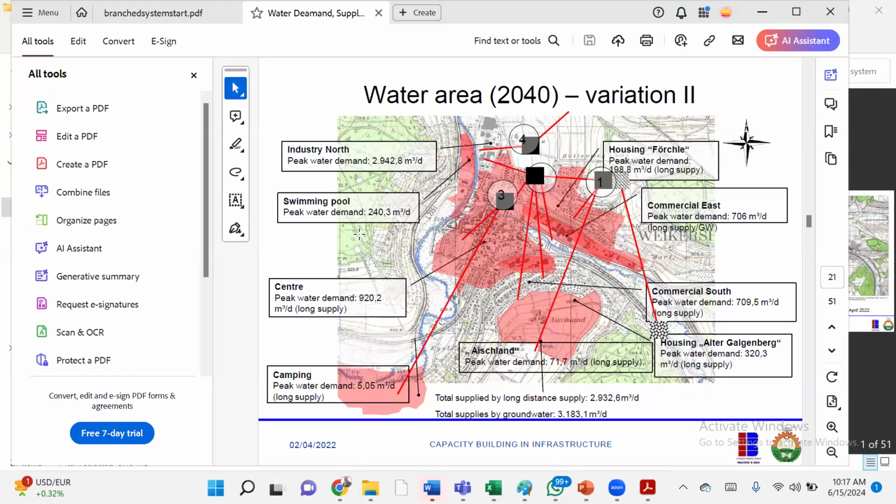So for industrial notes, what is this pipe size? And for housing fortunately on the right, which is tank 1, industrial notes is using tank 4. It's a decentralized design. It's a decentralized design because when we started, we got to know that the land is not flat and the elevation difference is more than 8 bars. Therefore, we go into what we call pressure zoning. Some people call it phases, no problem. But the real technical word is pressure zones. Pressure zones, because everybody must not get water from the same elevation. Everybody must not get the water from the same source. Therefore, you need to zone them into appropriate communities so that there will not be excessive pressure.